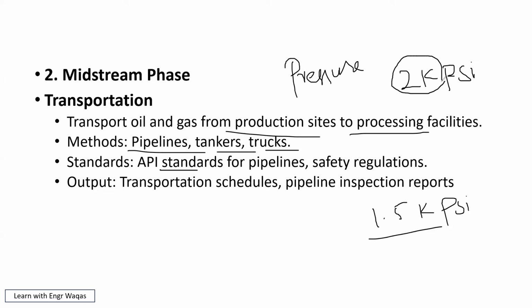So there is a designers team which can take reservoir samples, different kinds of wellhead flow samples, and measure how much wellhead pressure there is. They are going to monitor wellhead static pressure, dynamic pressure, flowing pressure, and collect the data on how much pressure is there. On the basis of that data, the pipelines will be recommended: how much safety margin, their material, safety regulations.